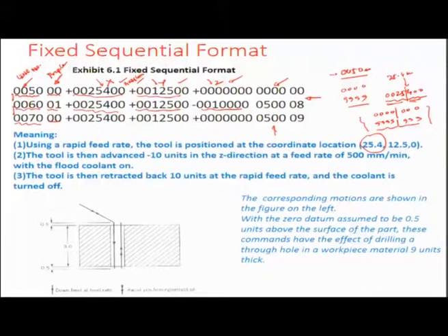So this could be recorded as the feed or the speed command, and these are some other operations which are, for example, related to the coolant or any other operation which are important yet not the main operation, okay, and these are known as the miscellaneous commands. So you can say that these commands correspond to the speed and feed setting aspects, and these commands correspond to miscellaneous aspects of machining. So there is a certain, fixed way in which numbers are in a line by line basis able to give a sequence of operation.